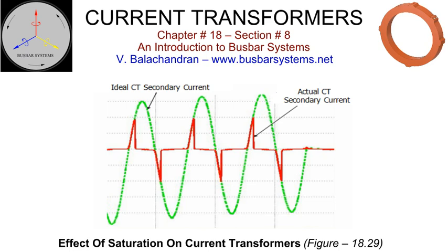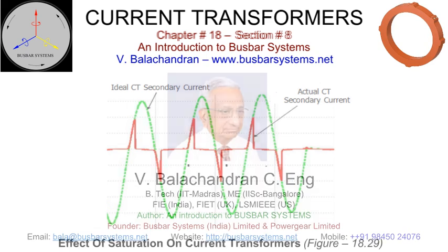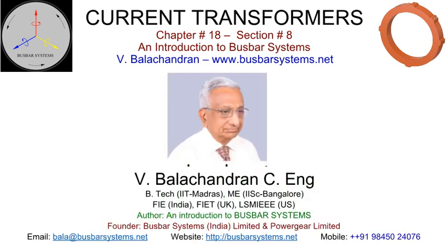A three-phase fault at the generator connection generates a highly asymmetrical short-circuit current waveform with a significant DC component. The effect of the DC component will be to shift the bias along the BH curve, resulting in an asymmetrical distorted secondary current waveform.